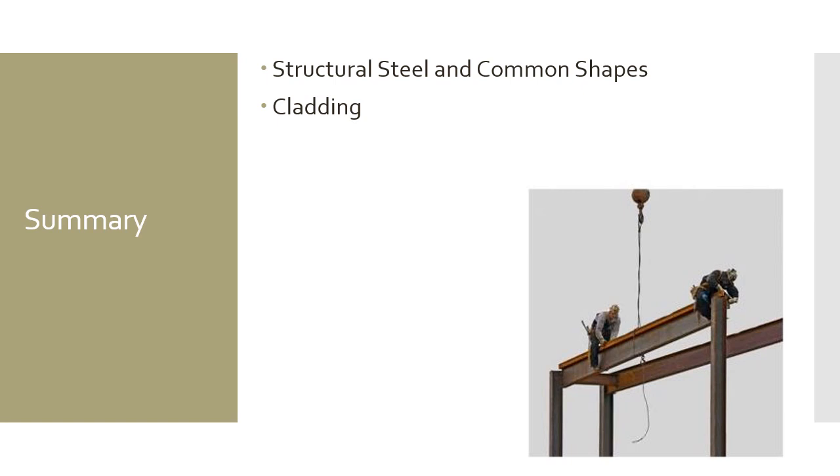Not so much where it's used, but that it does exist. And it just involves basically putting down a layer of stainless steel onto a carbon steel, or let's say a nickel alloy onto a stainless steel. There's a number of different variations in chemical or metallurgical directions you can go with cladding, depending on what is flowing through your pipe valve system.